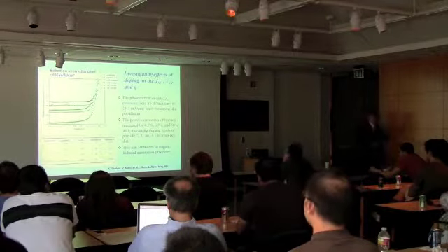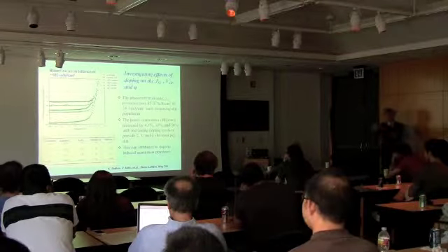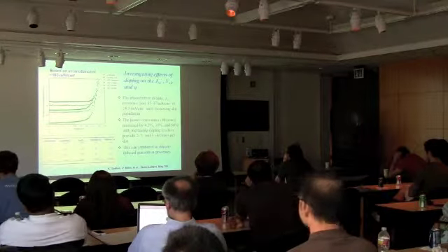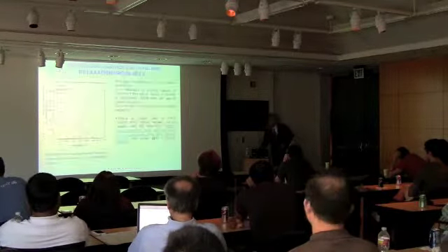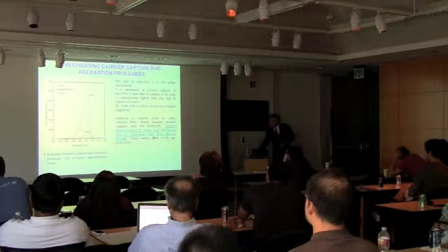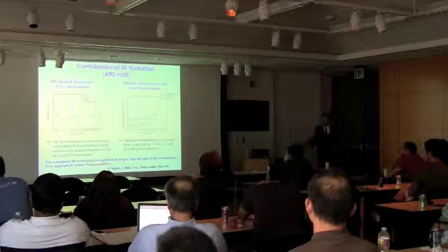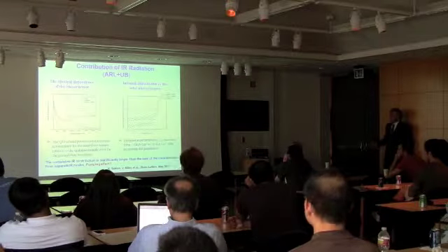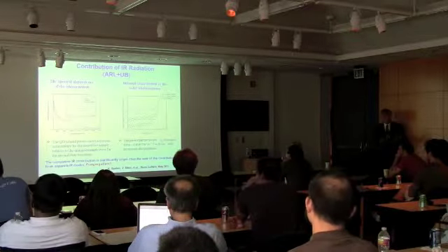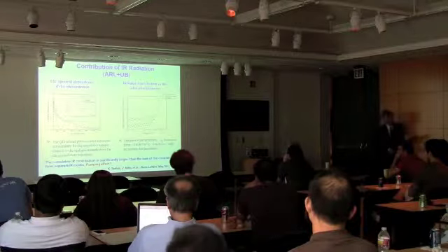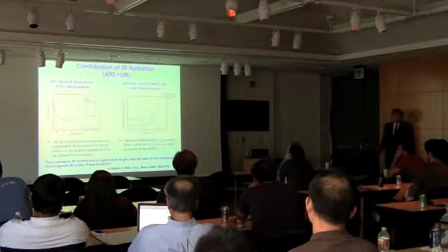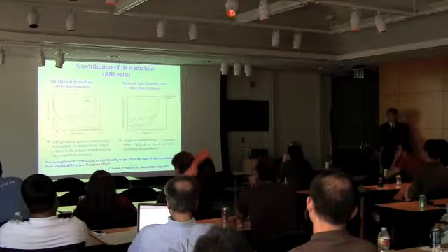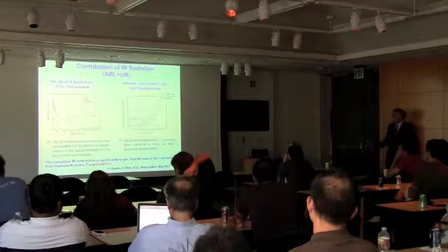So now we emphasize that it does not matter what your initial cell was. If it was with a higher current, you can always increase the current due to the contribution from the infrared. I will go back there in a minute. So here it is shown only the infrared contribution, and infrared we name everything with a wavelength above gallium arsenide. So we put on top of the material thick gallium arsenide that absorbs everything. It doesn't go to the solar cell. Whatever gallium arsenide passes goes to our solar cell.